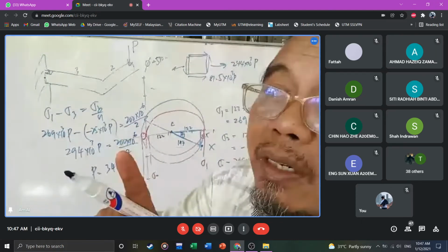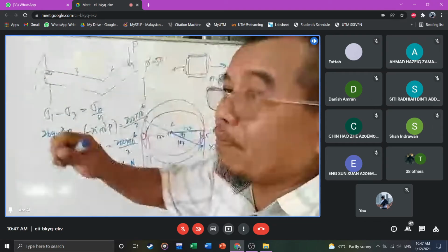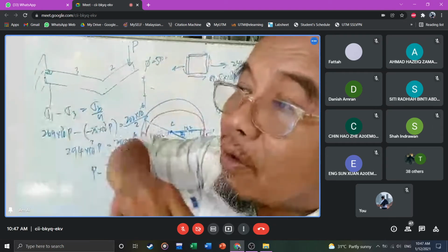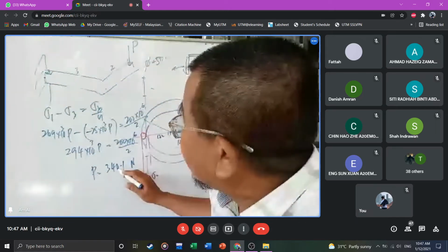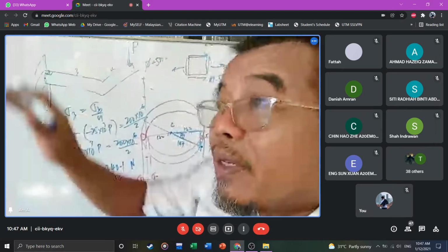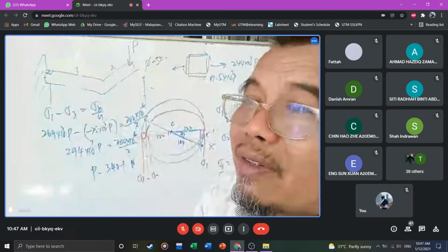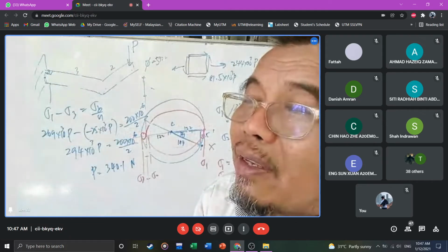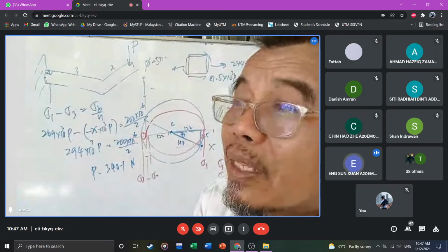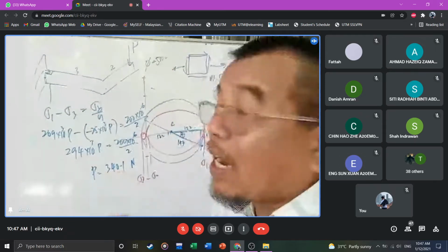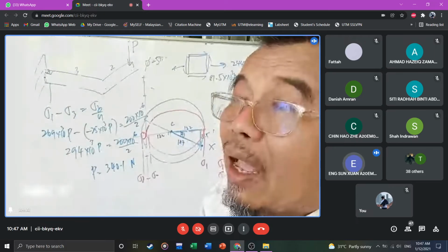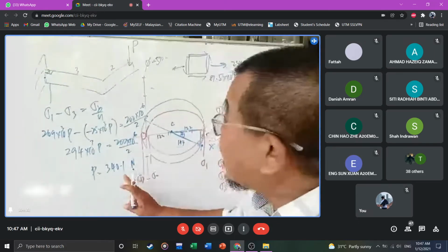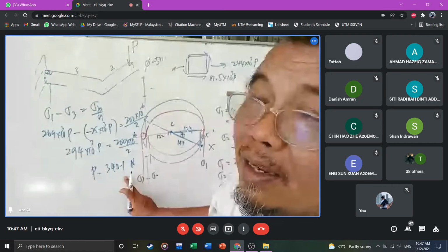Logic, not? For 50 mm, about that size, 3 meter long, and put a load of 34 kilogram. Bending, not? Are you with me? 34 kilogram is 340 Newton, right? Yeah, something like that. But this is with a safety factor of 2, not failure.